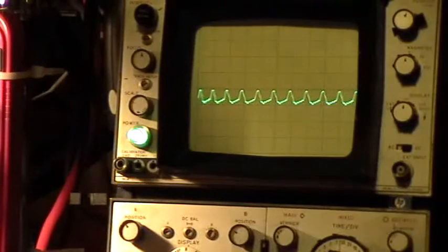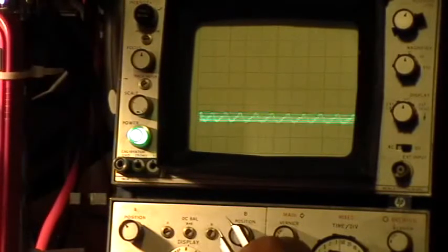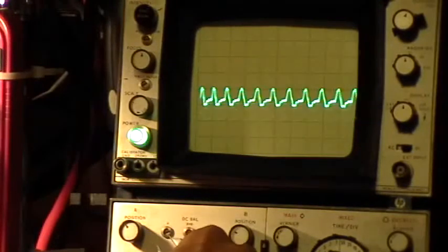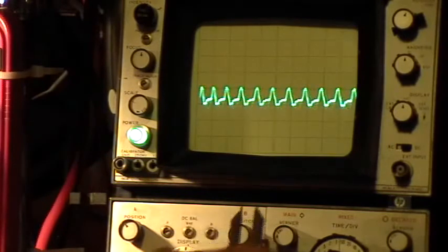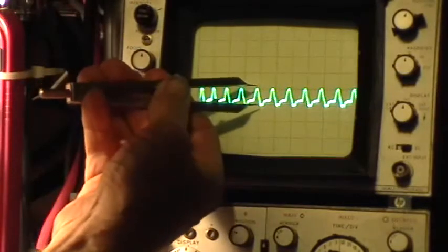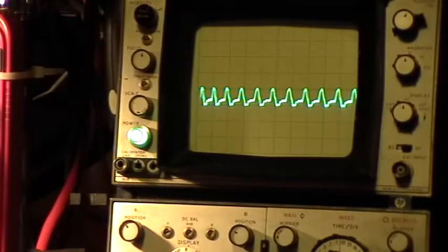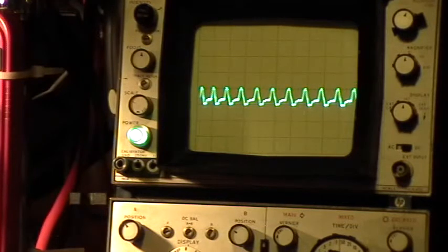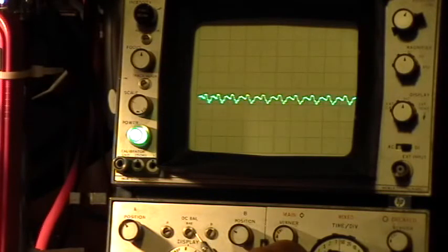Now I'm going to go to the negative pole of that battery, there, and let's go ahead and switch the scale now. Okay, so at 5 volts per division now, we have an amplitude of 1 full division, which is 5 volts. Now I'm going to go to the other side of that jumper. Boom. That's another 5 or 6 inches of wire and a couple of connectors.